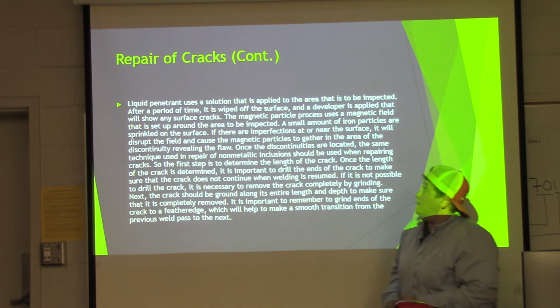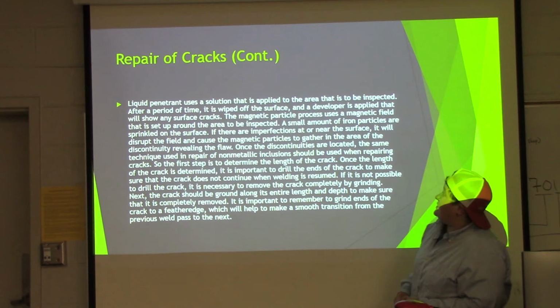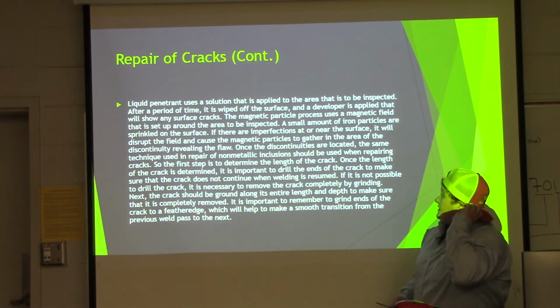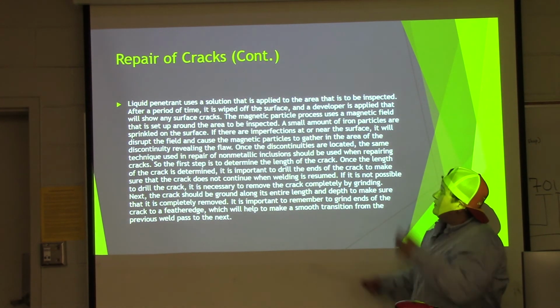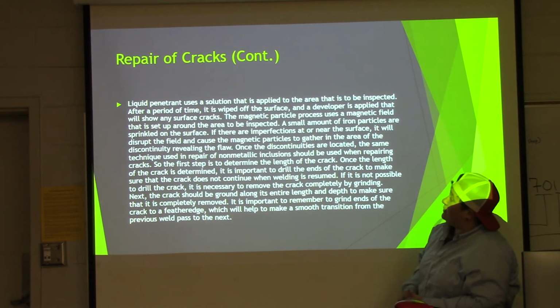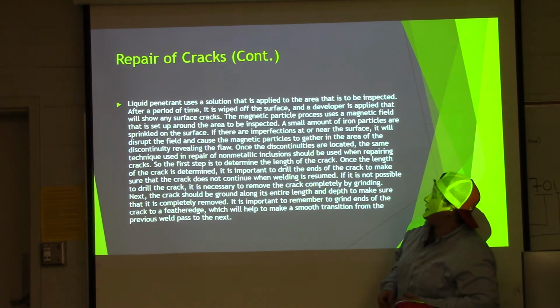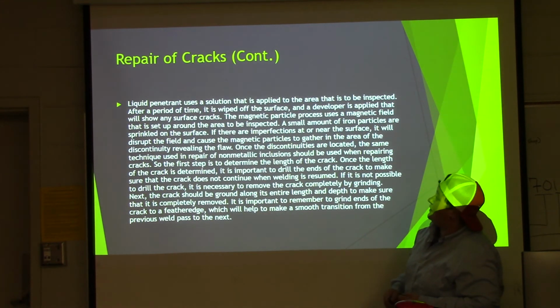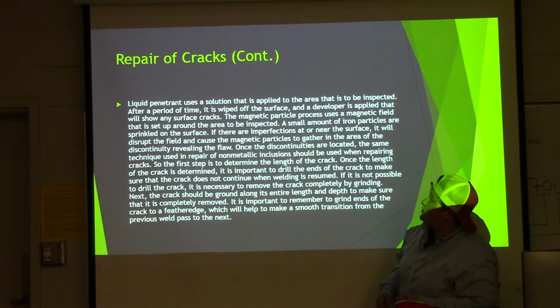Repair of cracks continued. Liquid penetrant uses a solution that is applied to the area that is to be inspected. After a period of time, it is wiped off the surface and a developer is applied that will show any surface cracks. The magnetic particle process uses a magnetic field that is set up around the area to be inspected.